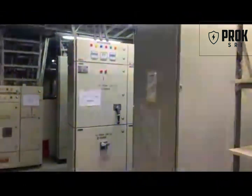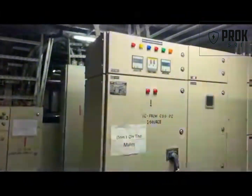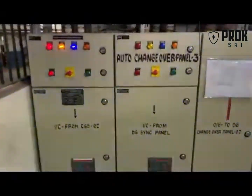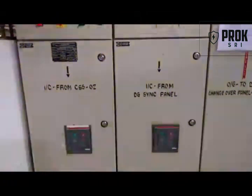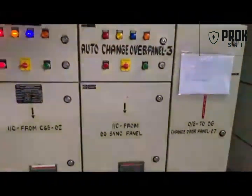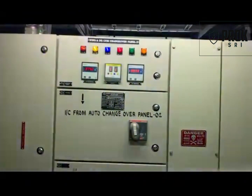We are now entering the panel room where the auto source changeover panels are placed. In this particular panel, there are two incomers. One incoming is from the EB mains or infinite bus. The other is from the DG or the finite bus, and one outgoing to the DG changeover panel.